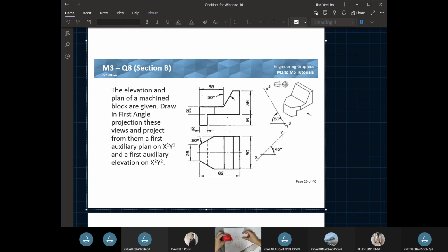Does the height change even if you look from any angle? No. So you can mark out the height first. This is 15 cm. You can mark out all the heights. For example, the front of this shape, you can transfer to here. This length, transfer to here. That is the first step.